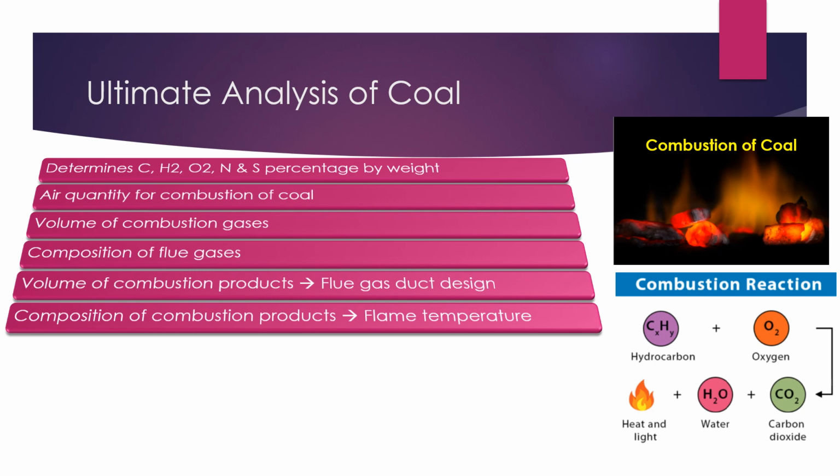How much volume of combustion gases or flue gases will be generated, and what the composition of the combustion gases will be, are also decided from the ultimate analysis. Flue gas duct design can be done by knowing the volume and composition of combustion gases. Flame temperature can also be determined from the composition of flue gases.